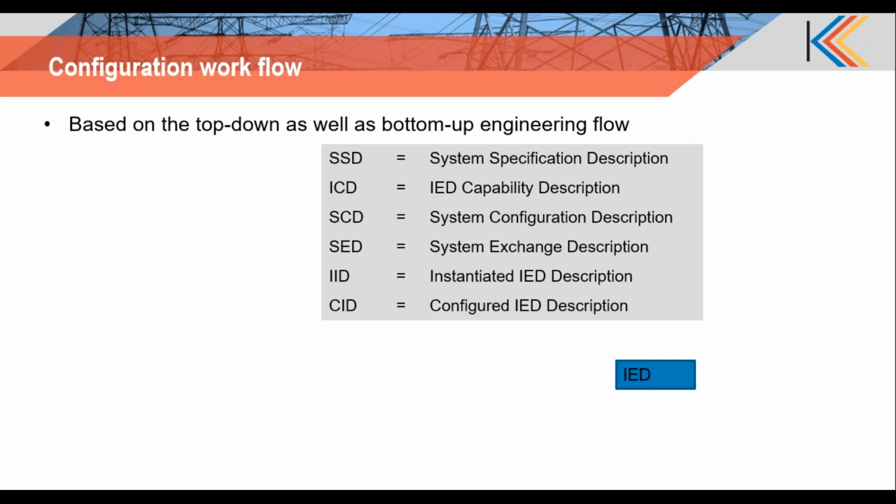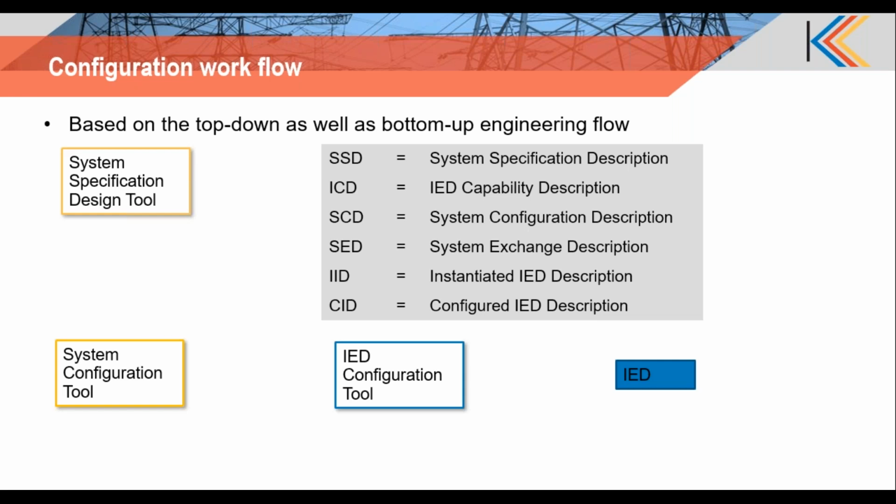So you'll be wondering why do we require so many configuration files? So you have an IED configuration tool, and the IED configuration tool is generating something called a CID, the configured IED description, which is downloaded into your IED. So that's the straightforward programming or engineering concept.